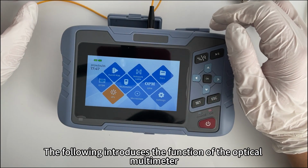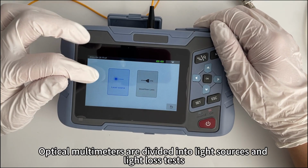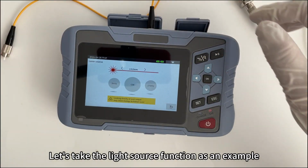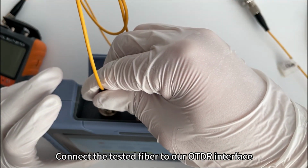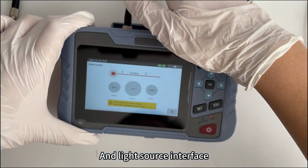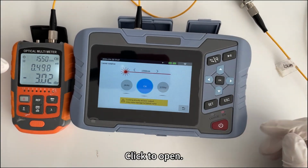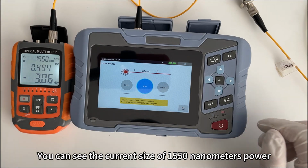The following introduces the function of the optical multimeter. Optical multimeters are divided into light sources and light loss tests. Let's take the light source function as an example. Connect the tested fibers to our OTDR interface and light source interface. On the other end is our optical power meter. Click to open. You can see the current 1550 nanometers power.